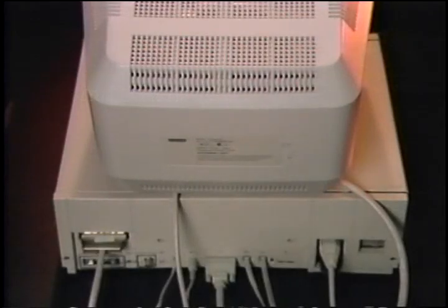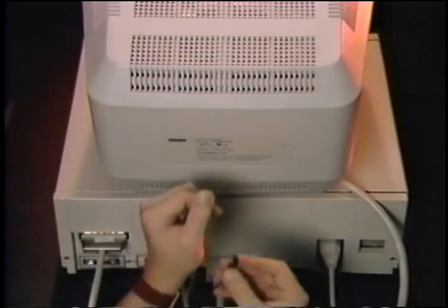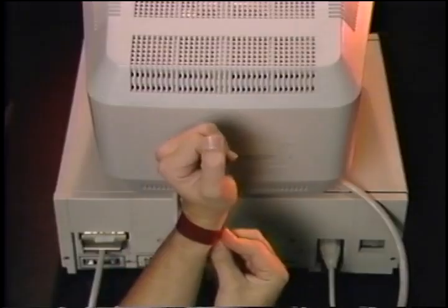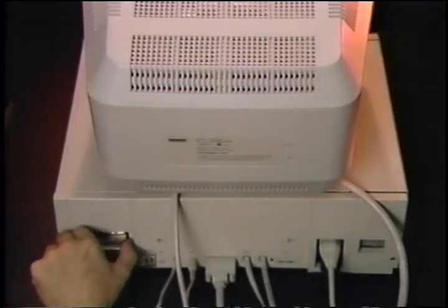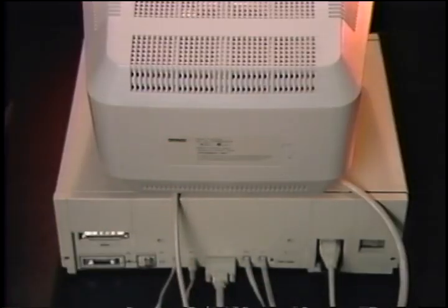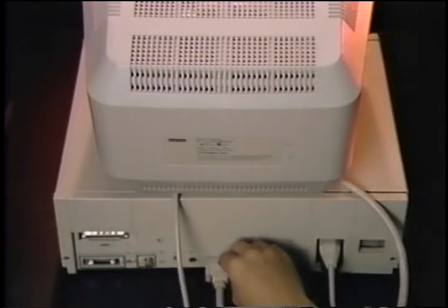Because the VAXStation 3100 utilizes CMOS technology, the system is sensitive to electrostatic discharge. Always prepare a static-free environment. A service design feature is that the I/O cables can be left attached for most device replacements.